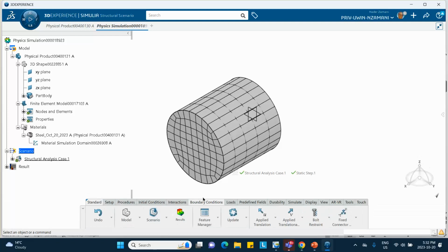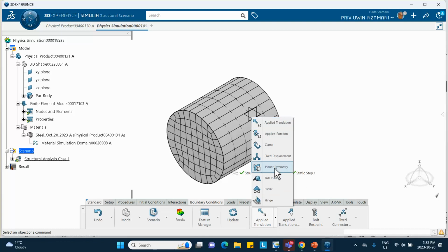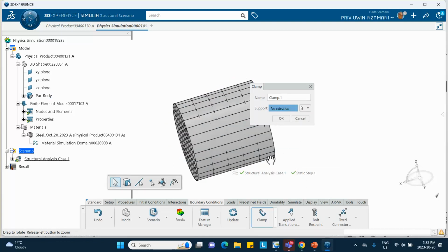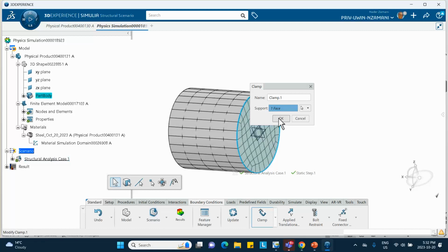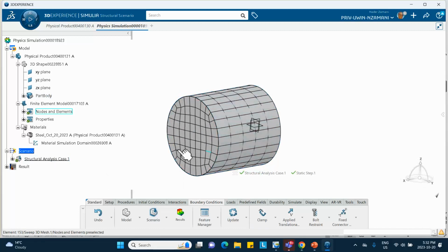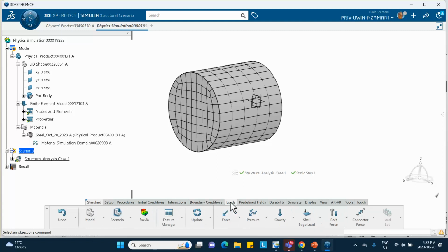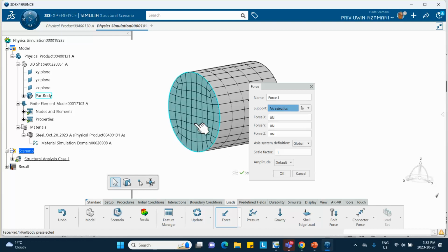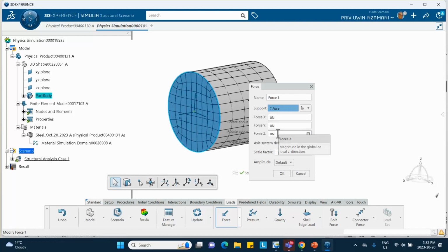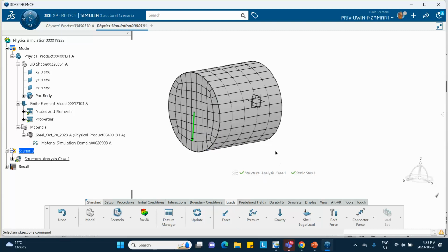For example, let's hypothetically say that we clamp the right side. Where is that clamp? For example, this side. All right. And then we apply maybe a downward load here. So downward force or something like that. Load, let's say a force on that face in the direction Z minus, these are all dummy numbers, minus 1,000 newtons, okay, good.